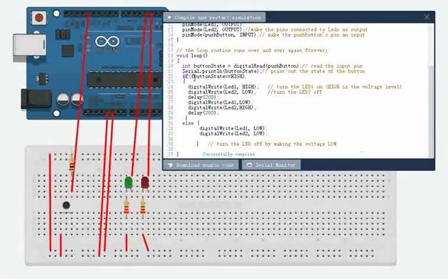Then we're going to use a very clever statement called if, which is very important whenever you write code, because the if statement allows you to make a decision. In this project, we ask Arduino if the button state equals HIGH, and then we do something. We use the curly brackets to group lines of code together.